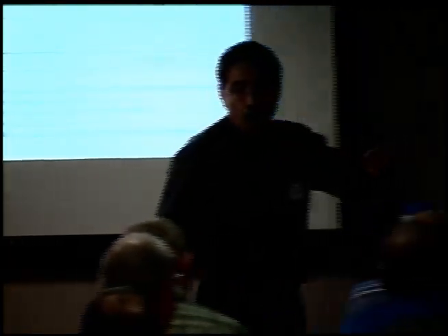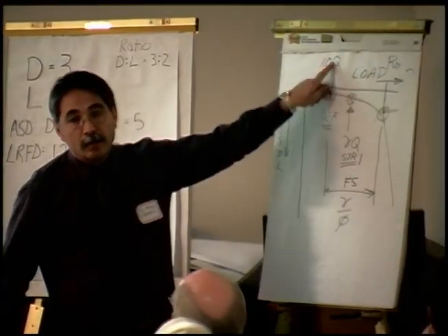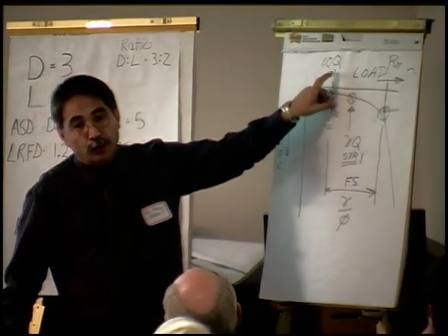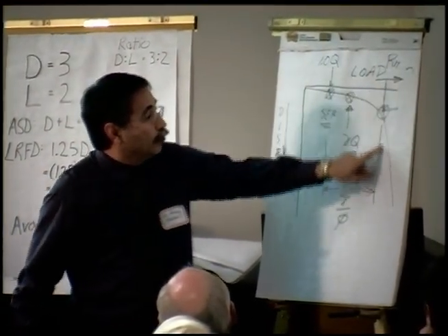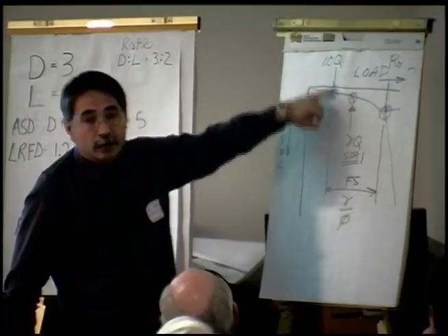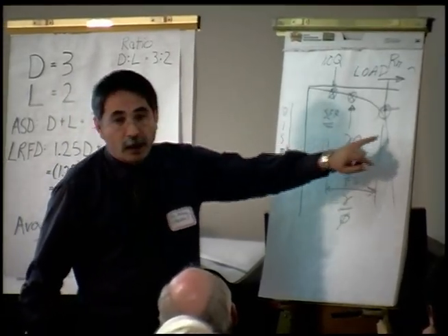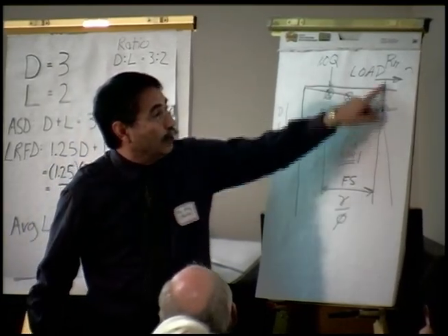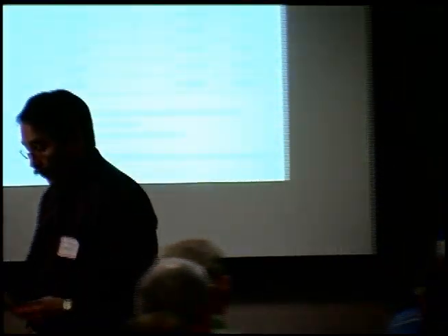Historically, what it did before was give you the service capacity, which was here, right? And if we were using a factor of safety of 2.2 for wave equation, then if this was 220, then this would be 100 ton right here. It's just whatever the ultimate is divided by 2.2. Now it's giving you the ultimate or nominal capacity as the number coming out of that Blue Book.